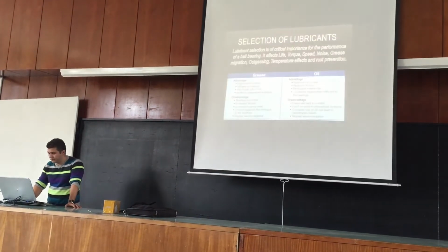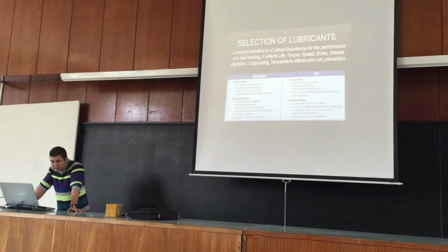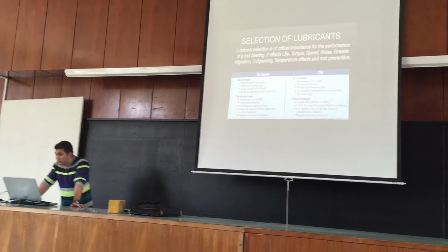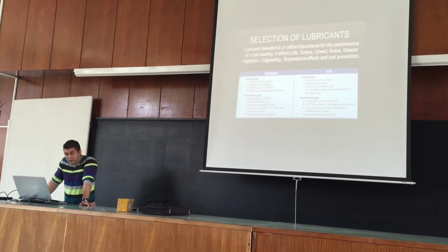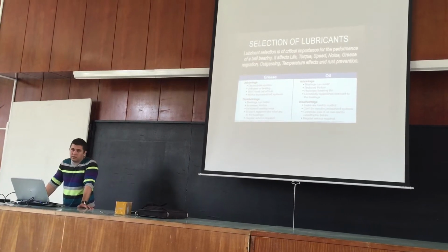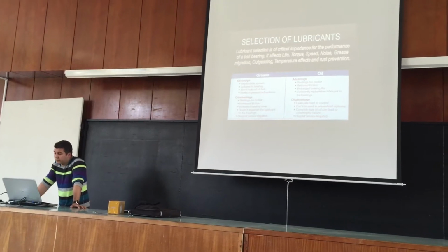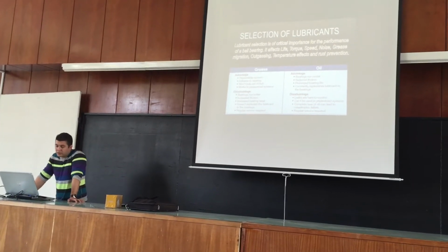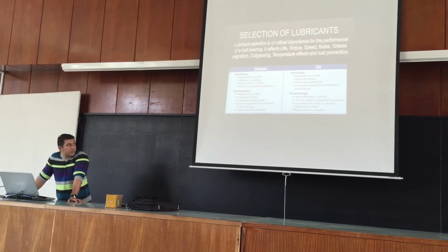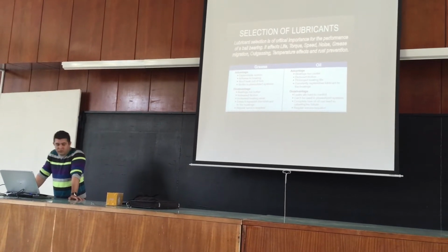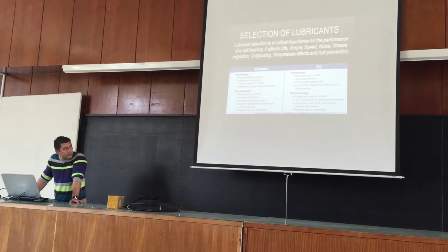So the other subject is selection of the lubricants. This is critically important for performance of ball bearings and affects life, torque, speed, noise, grease migration, outgassing, temperature effects, and rust prevention. So they also have some advantages and disadvantages.